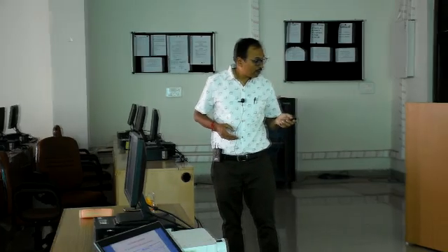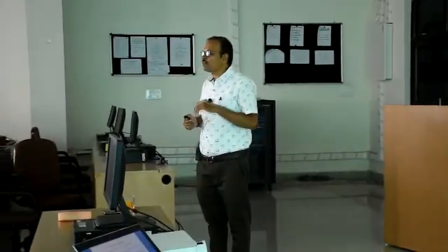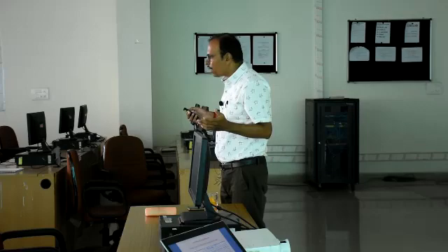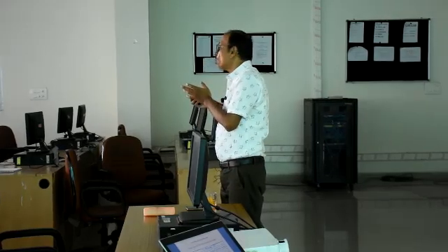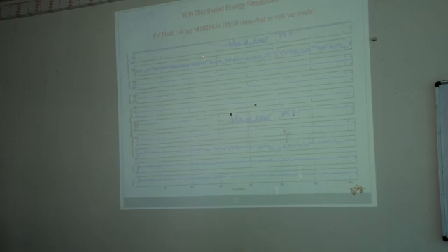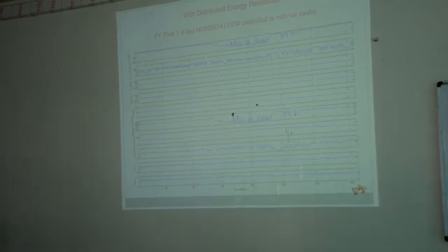And the issue is that if you look at from this point to this point, that PV is not producing any power. Okay, it means PV plant is not producing any power because either you are in the night time or you are at the beginning of your day. So most of the time your PV plant is idle. Okay, this converter is not utilized for any purpose. So what you can do, you can take the capacity of this PV converter to either supply the reactive power or inject the reactive power to your grid during this time.